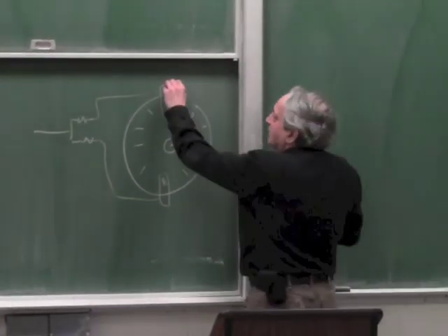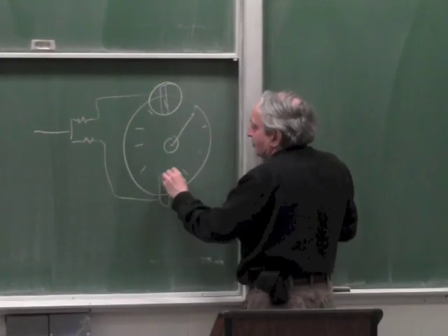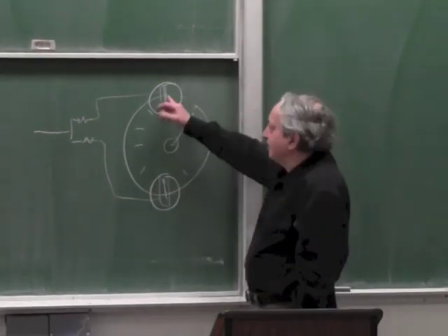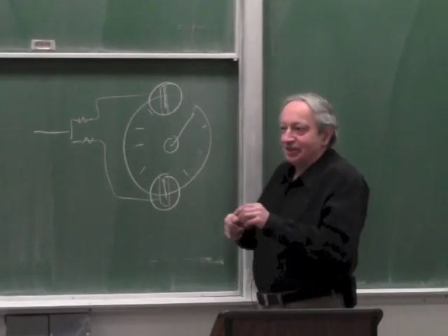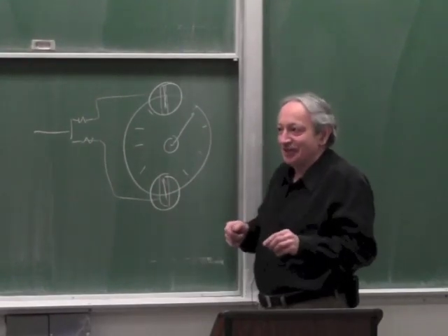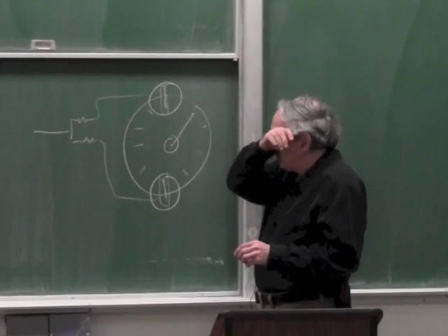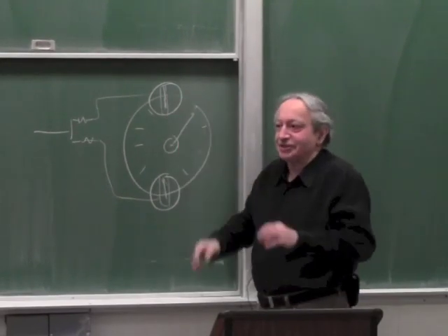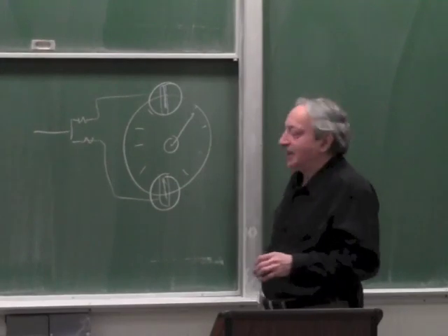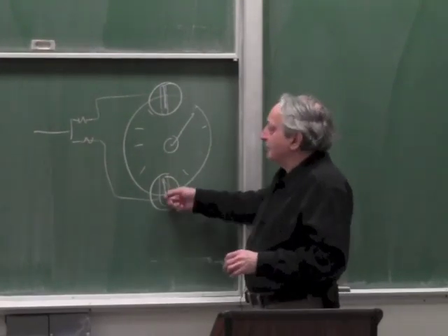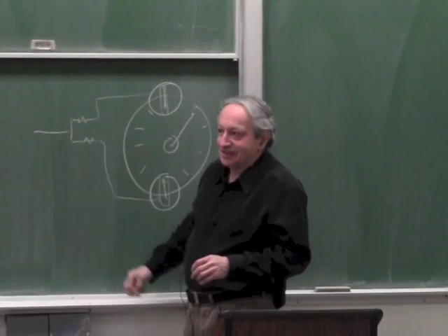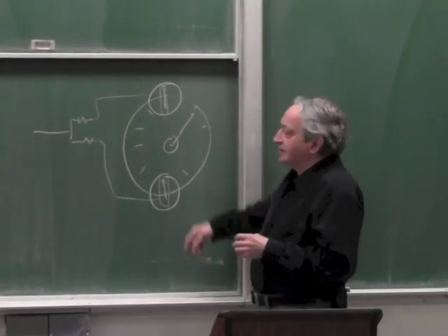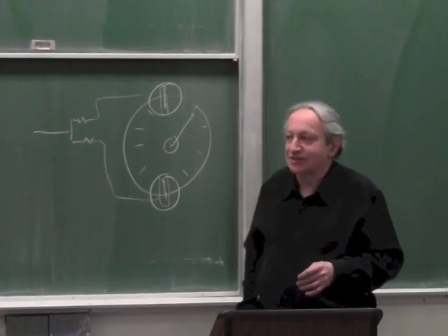It has two eyepieces, so the user takes a reading from here, a reading from here, and manually averages them together. In the more modern theodolites, this image was superimposed on this image, so the averaging is automatic, and the electronic theodolite is just two electronic readouts connected like this. But the principle of averaging to cancel the error is 100 years old.